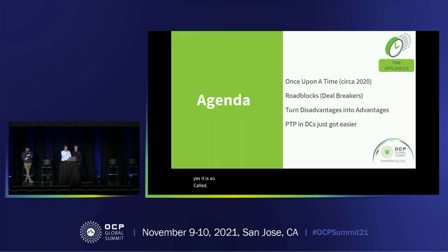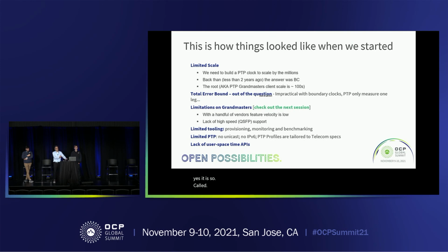And second, on your normal Ethernet NIC out of that Grandmaster server, what is your accuracy? Are you looking at class C, or even close to a class D that is yet to be fully defined, or are you basically just class B and you don't care, class B is fine enough?